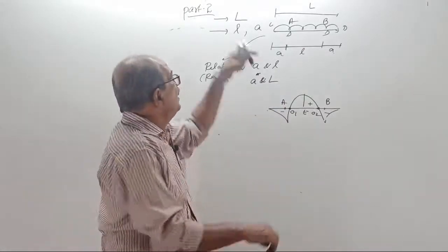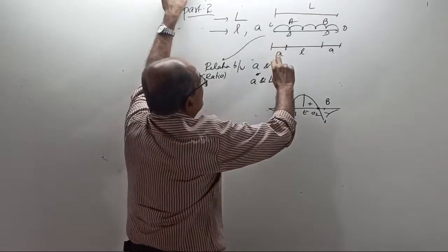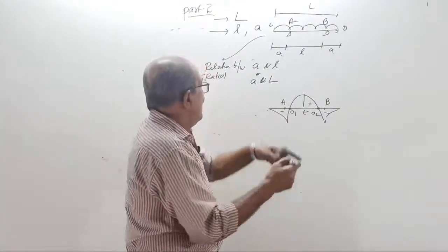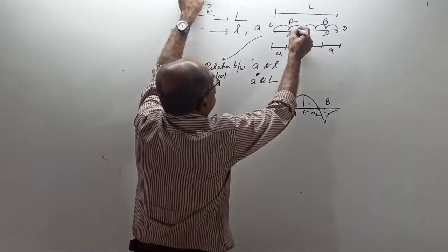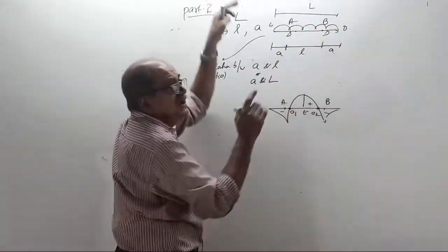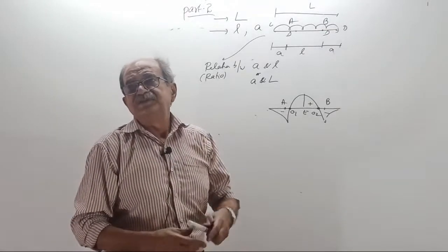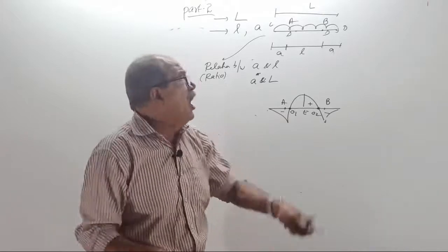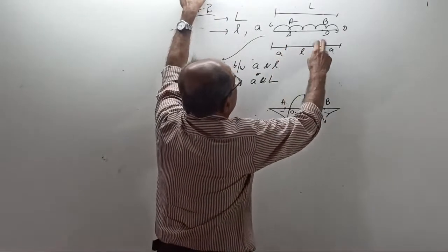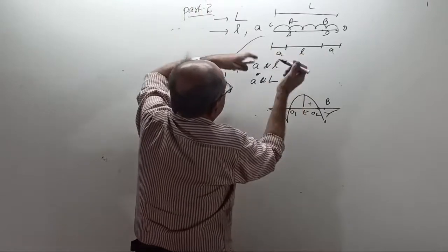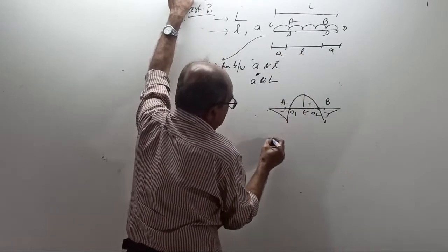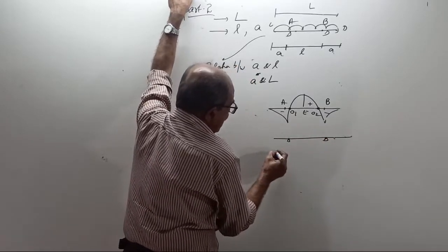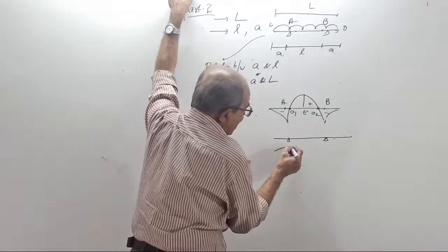Wrong statement. The overhang will hog. The hogging will continue for a further distance, till the point of counterflexure. Sagging will be only between the points of counterflexure, not that A to B fully sags. Steady. It means the beam is like this. This is a technical matter. So many make the mistake here. It is hog, still hog, then stops.